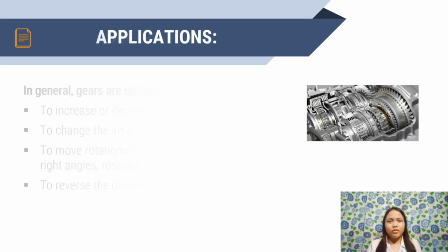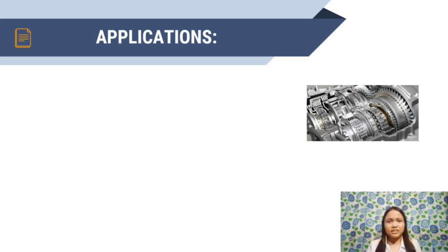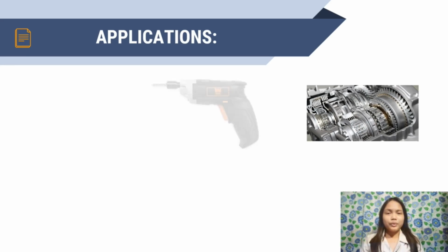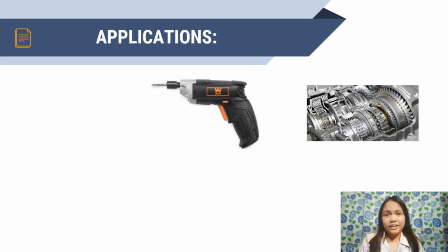Gears are included in a wide variety of mechanical devices. They provide a number of critical functions, the most important of which is to reduce the gear ratio in motorized machinery. This is so important because a tiny motor rotating at a high speed can often generate adequate power but not enough torque for a device. An electric screwdriver, for example, has a high gear reduction because it requires a lot of torque to turn screws, but the motor only provides a tiny amount of torque at high speeds. The output speed can be reduced while the torque is raised using a gear reduction.